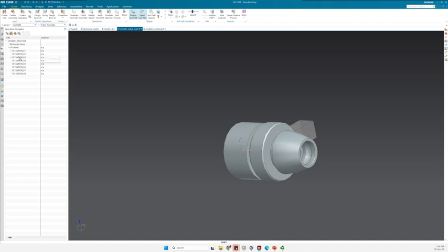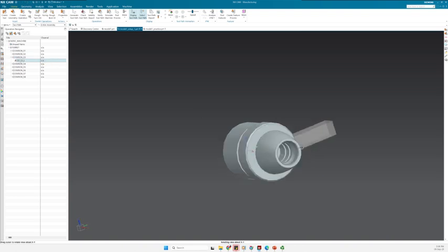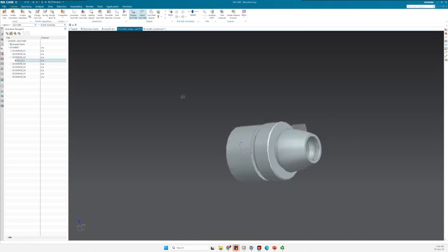This doesn't necessarily mean that it is colliding. It is just the visualization, because now we don't have any offsets or anything defined. And also another outside diameter tool, for example, length 55, in station 3. So I can already see that outside diameter tools are defined on the odd numbers.